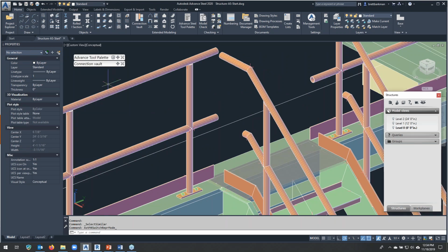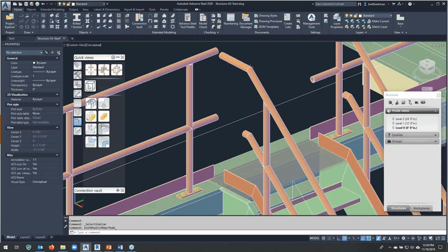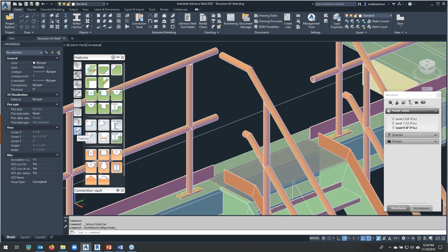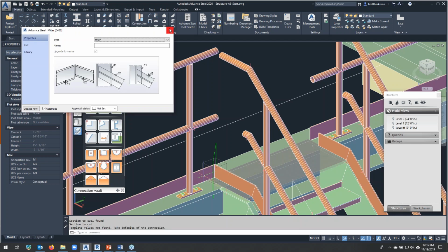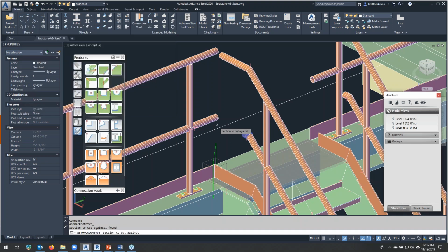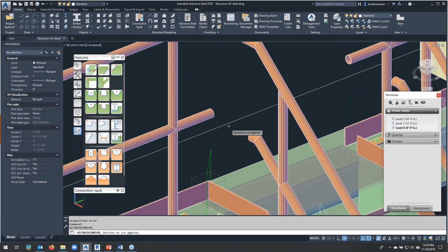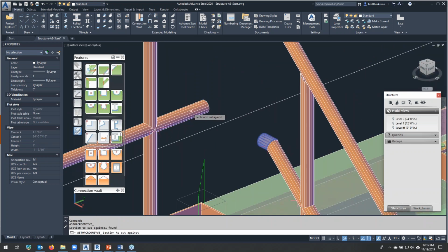And so now we can do some mitering on those railings. You'll find miter under the features in the Advanced Tool set. And miter works on just about anything. Always pick the objects involved. And if you want to work on the settings there, that's fine. Usually I wind up just closing it because all I want to do is a good old miter. And if you find yourself having trouble selecting, you may just need to zoom in a little bit.